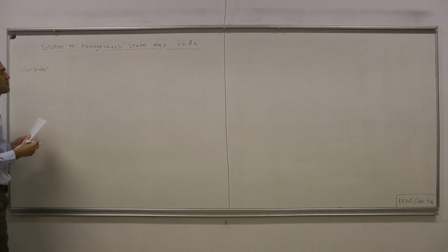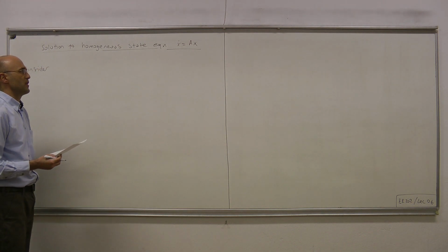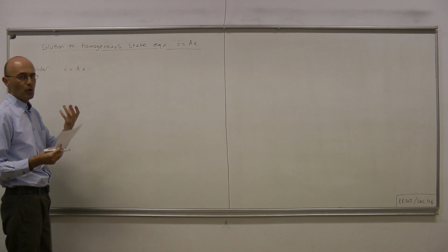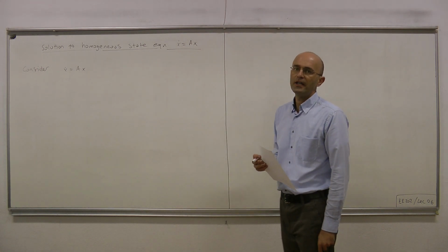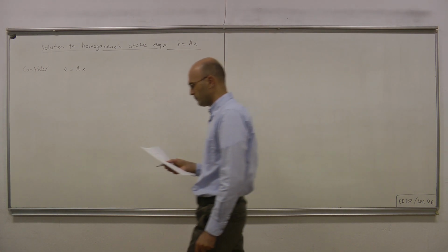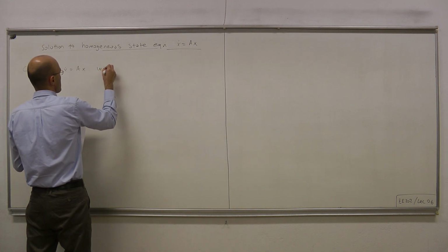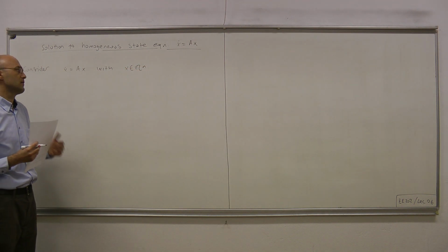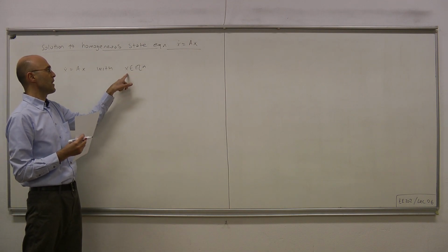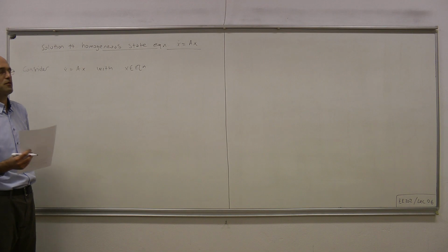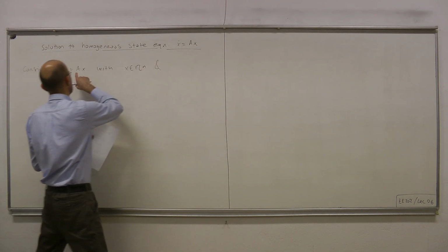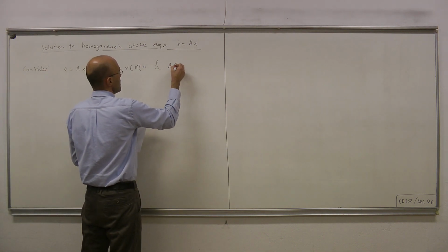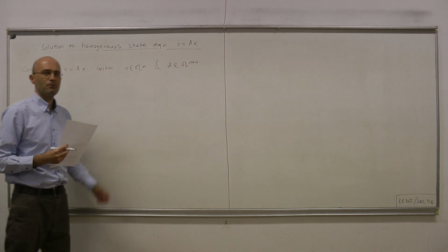Now, suppose we have obtained somehow, or perhaps been given, the state equation for some LTI circuit. x dot equals Ax, where x contains our capacitor voltages and inductor currents within our circuit, with x in R^n, suppose that we're talking about a circuit of order n. So our state vector x is of size n, and that makes this A matrix, which is always a square matrix, of size n by n. A is an n by n real matrix.